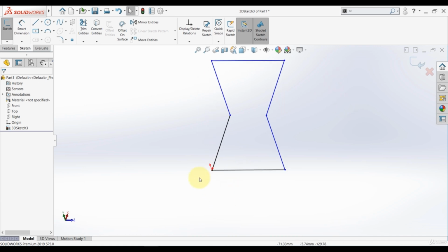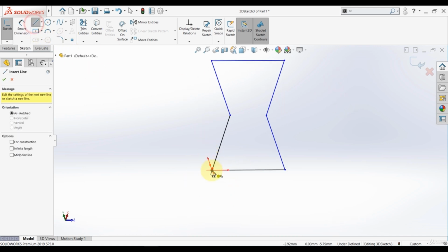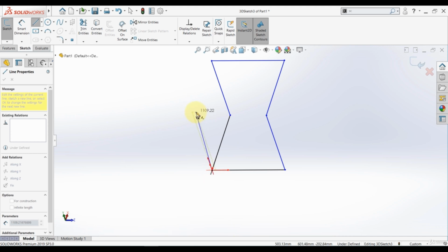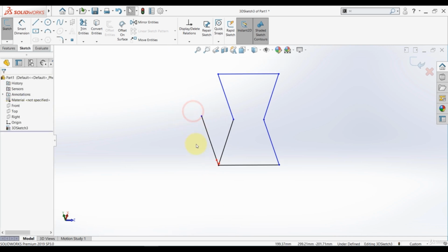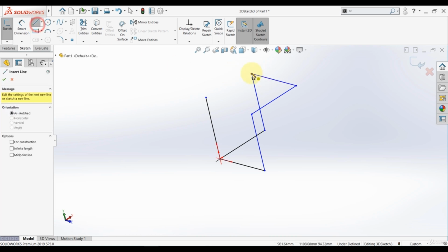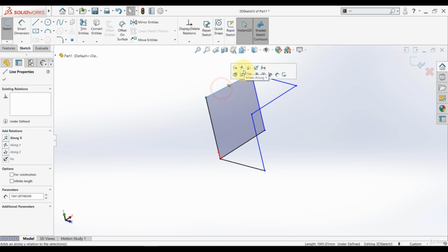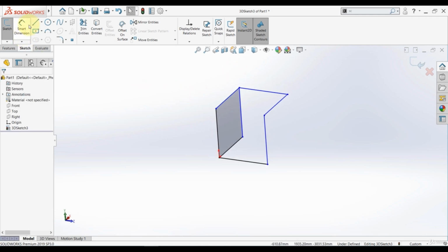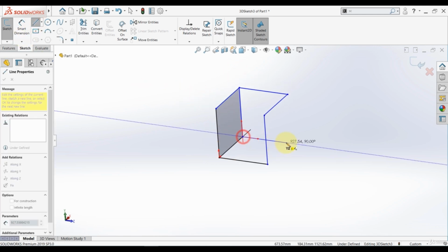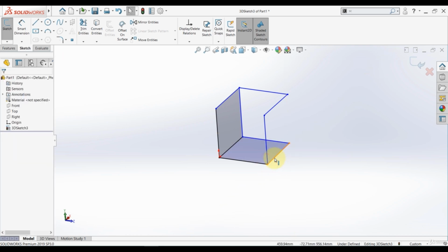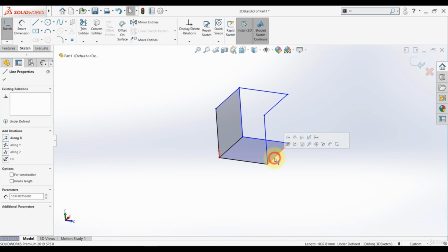Now, let's finish creating this cube. So start here again, and make sure you go on the Y direction. Now connect these. And this line should go along the X axis. So select this line, and then make along X. Now, we need another line here, then hit the Tab key so you can connect it here. Now this line should be along the X axis, so select it and make along X.